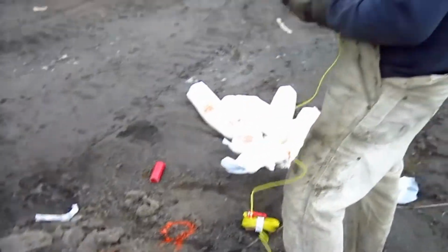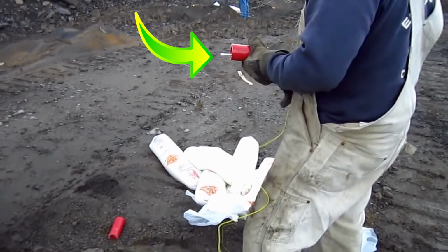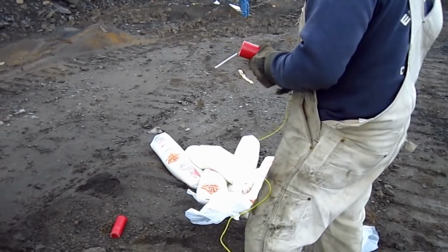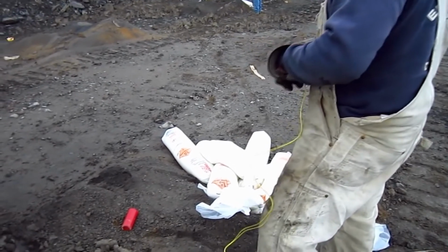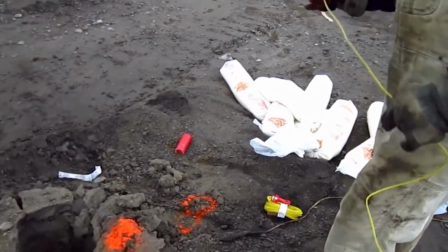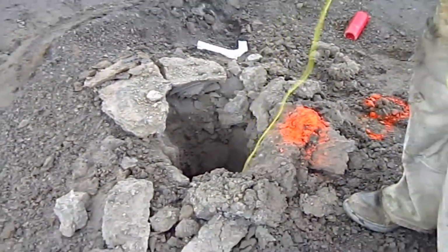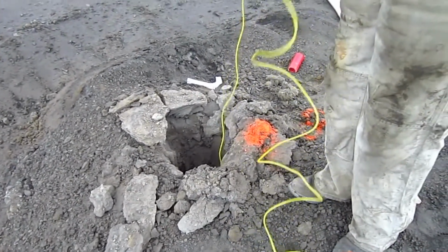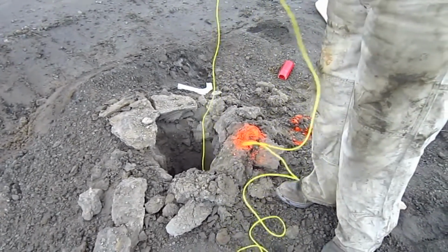Then the operator is preparing the blasting cap. This is the silver rod connected to the yellow wire. This will ignite the shot, mainly the red TNT cap. He passes it through the TNT and inserts it back into it to make sure it will not come off. He then drops the cap and blasting cap in the hole, making sure it reaches the very bottom. The yellow wire is a so-called shock tube detonator, or non-explosive fuse or initiator, in short, the Nonel detonator.